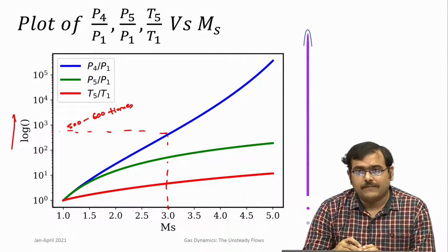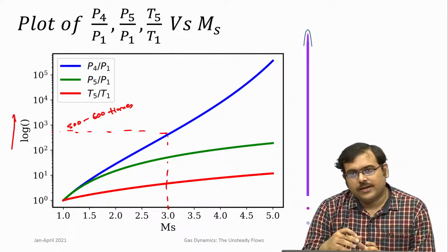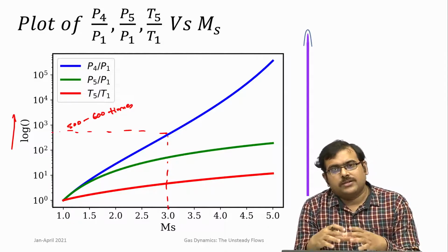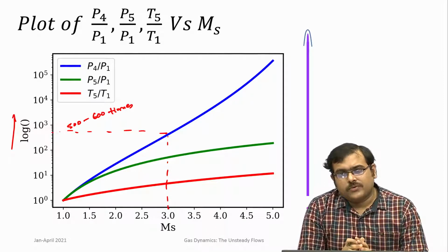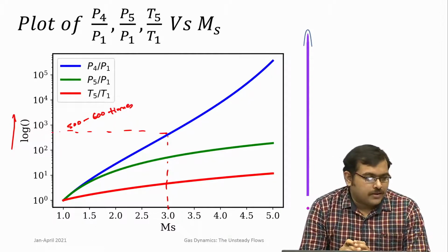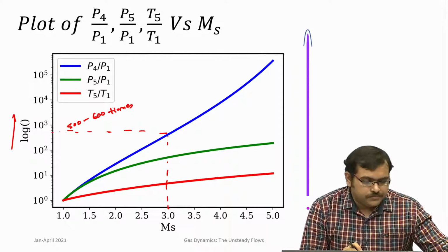For the same pressure ratio, the temperature ratio produced by an isentropic compression will be less. This is particularly useful for certain aerodynamic testing at very high enthalpies and high Mach numbers typical to hypersonic flows. So that is where this is quite useful.